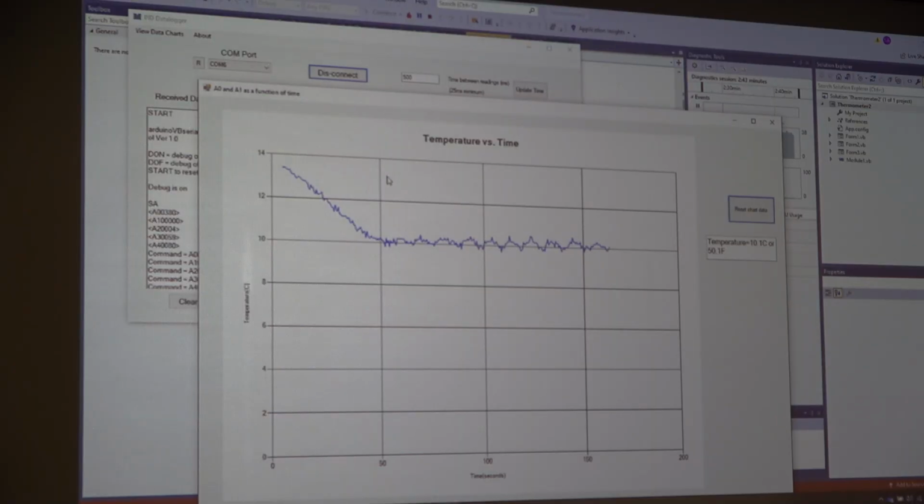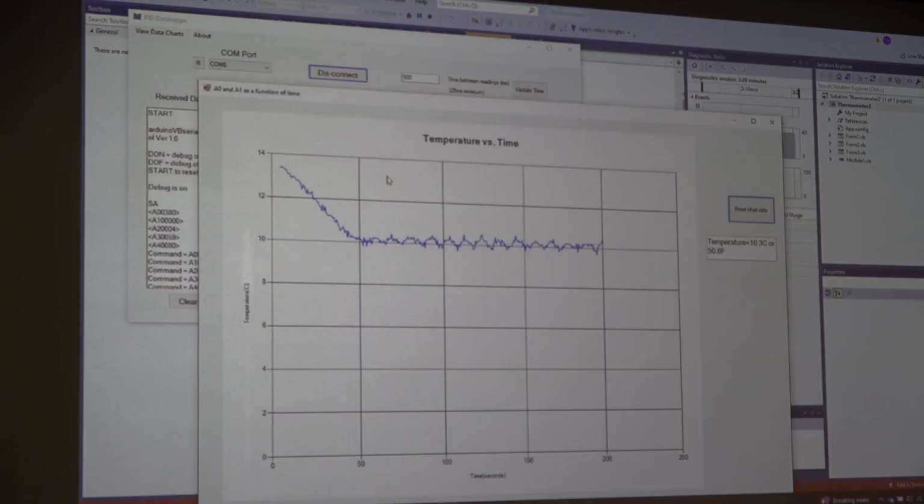D acts like a damping. So if I'm approaching my set point too fast, that's where you can put derivative on to cut that throttle back. Okay, so you can actually use a negative coefficient. So as my rate of approach gets faster and faster, well, it's constant. Probably want to do some math in there. But if my rate of approach is too fast, then D allows you to pull the throttle back so that you don't overshoot and ring.